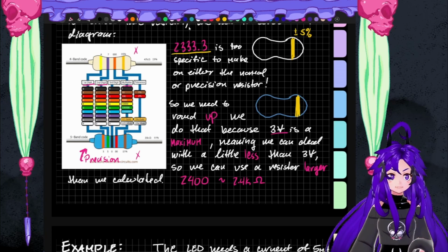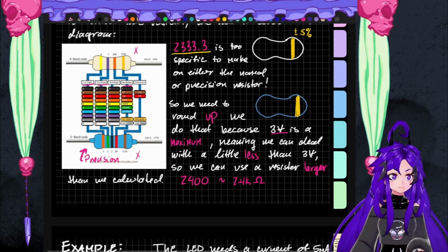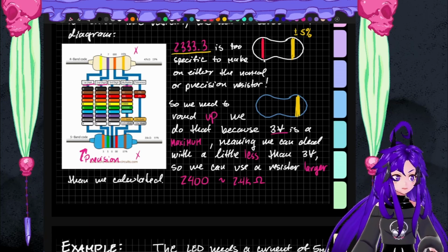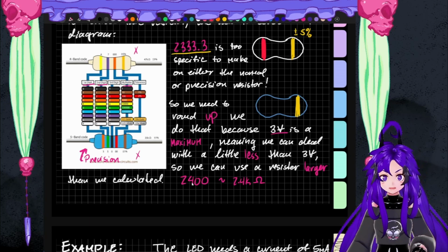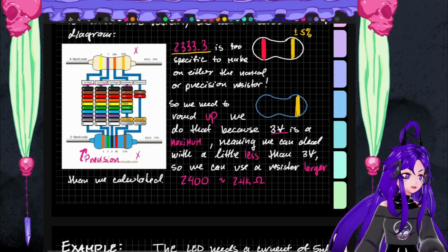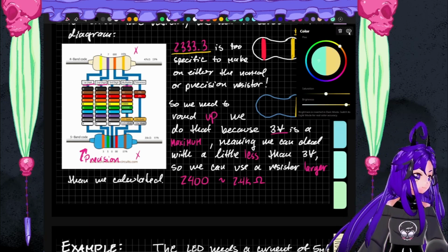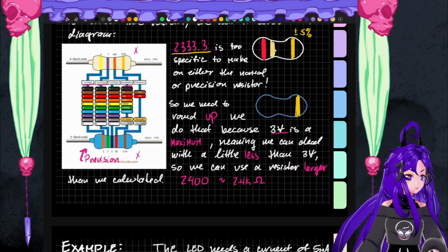So, first thing we're going to do is say we got 2 as the first digit. 2 is red. So we're going to choose one with a red band in the front. Then the number we've got is 4, which is yellow, and I'm going to try and pick a yellow that is not our gold. There we go.